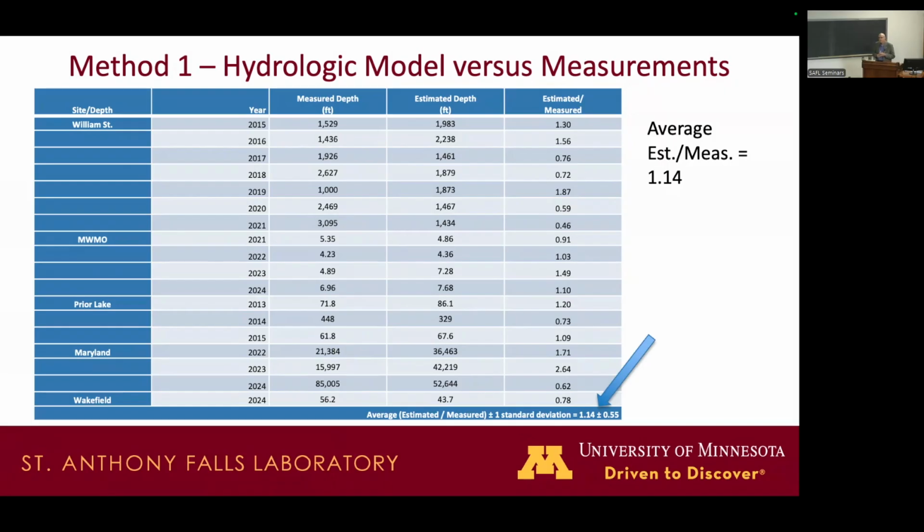One of the biggest problems in terms of measuring flow is that most people measure flow with an acoustic Doppler velocimeter. Now, an acoustic Doppler velocimeter is inaccurate below 4 inches. So you've got that much water coming out of whatever your treatment device is, and your measurement is inaccurate. Below 2 inches, it doesn't work at all.